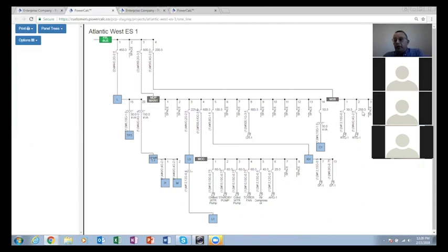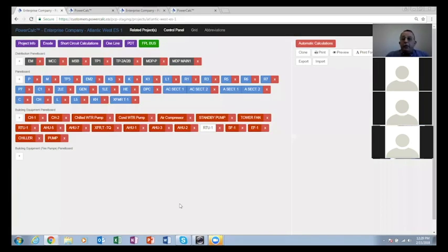I just kept it the same here so you can see, once I adjusted the number, the load, it adjusted the kVA, the trip, and adjusted also the conductor size. So again, everything is happening in real time for you. And I guess with that, I would leave the floor for any questions anybody has. Any question, anybody?